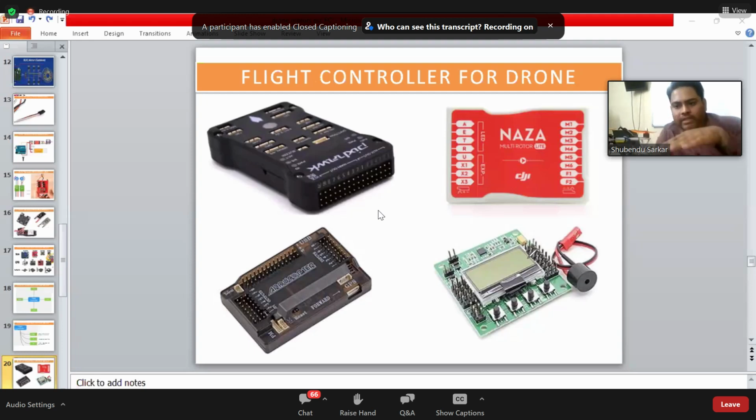But if you are seeking position holding and altitude holding and stability, no, it's not going to give you that much stability. Why? Because it doesn't have that many sensors present in it. It has a gyroscope and accelerometer, but in this KK2, I think there is no barometer. And due to the lack of a barometer, the self level of this drone is not good. Okay, that is the first point.